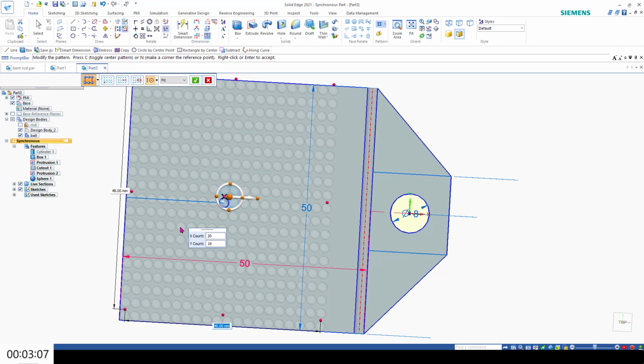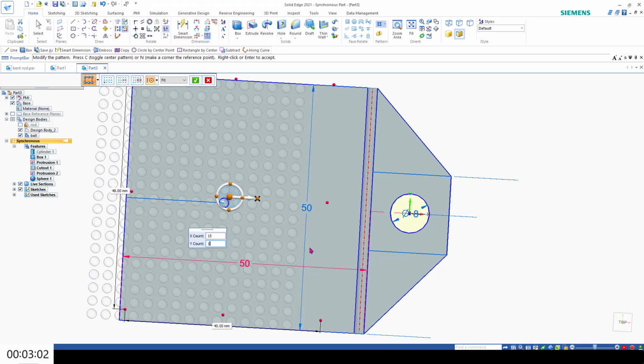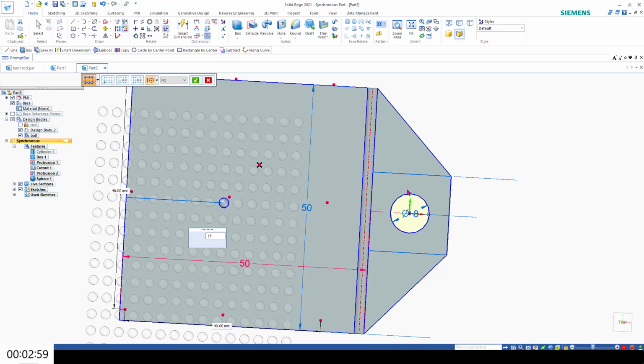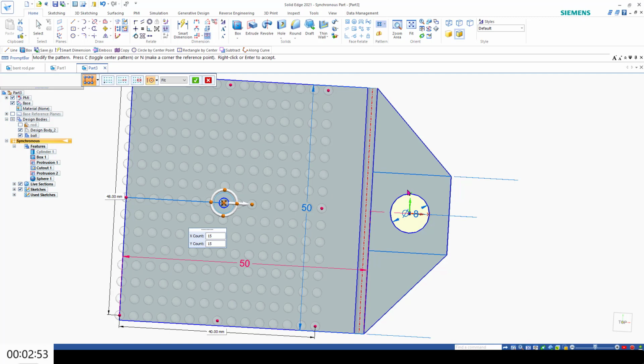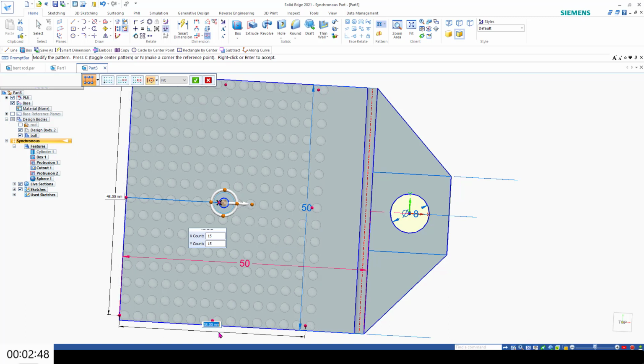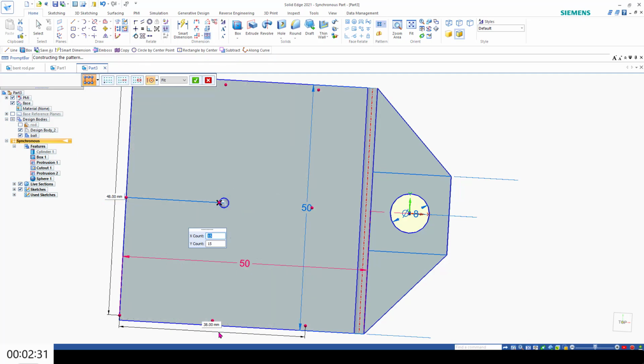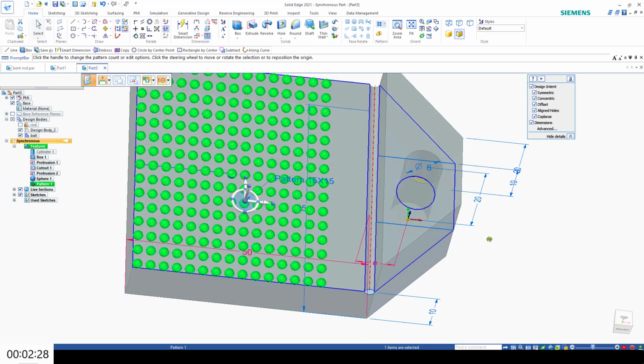All right, that's not bad, about 48 millimeters by 40 millimeters, and change the count to 15 by 15, just to get rid of those errors I was encountering with objects clashing. Doing the center again, and looking at it and thinking, okay, if I bring in just a little more, so 38, everything fits on the face. This seemed to work. I don't see any error messages or warning messages yet. And bang. All right, so 15 by 15 pattern.